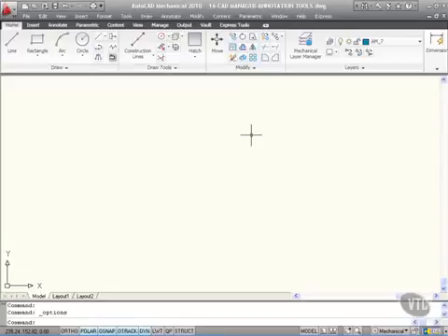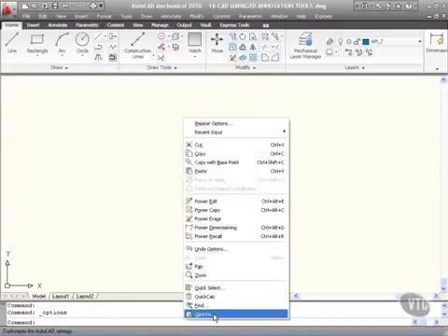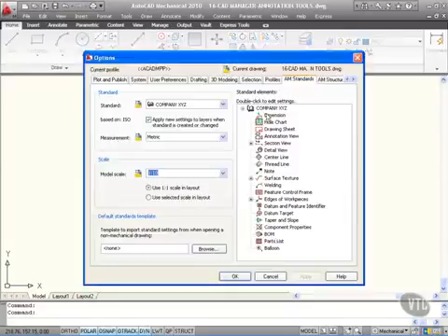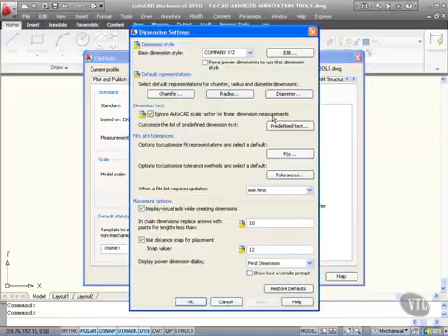The CAD manager can also benefit from the annotation tools available to him in AutoCAD Mechanical 2010. Again, these are based in your standard drafting standard. So, it's a right click down to options on the shortcut menu, and you'll notice this drawing is currently using the company XYZ standard. Now, if I double click here on the dimension setting, I can go in and work on my dimension settings and change the annotation and how it is placed on the drawing itself.